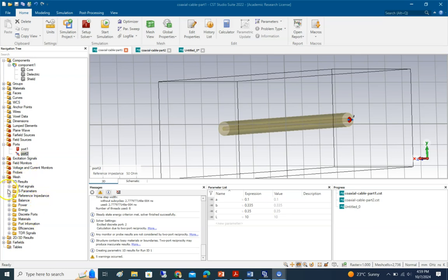So let's have a look into the S parameter things. Remember, although there are 4 S parameters, S11 and S22 have similar characteristics, and so do S21 and S12. The first pair is the reflection coefficient, the second pair is the transmission coefficient.